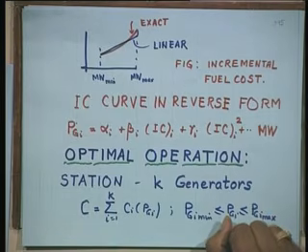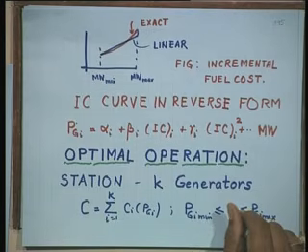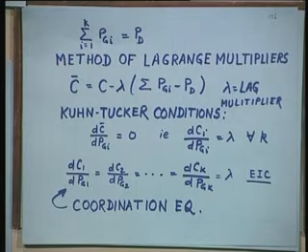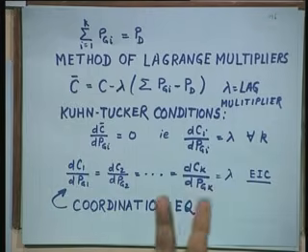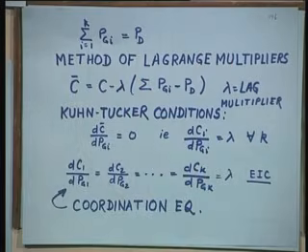The load balance equation was equality constraint and this is inequality constraint. Here this balance equation has no losses, because you are only considering Badarpur. There is no transmission losses. So, sigma of PGI must be equal to load which is coming on Badarpur.